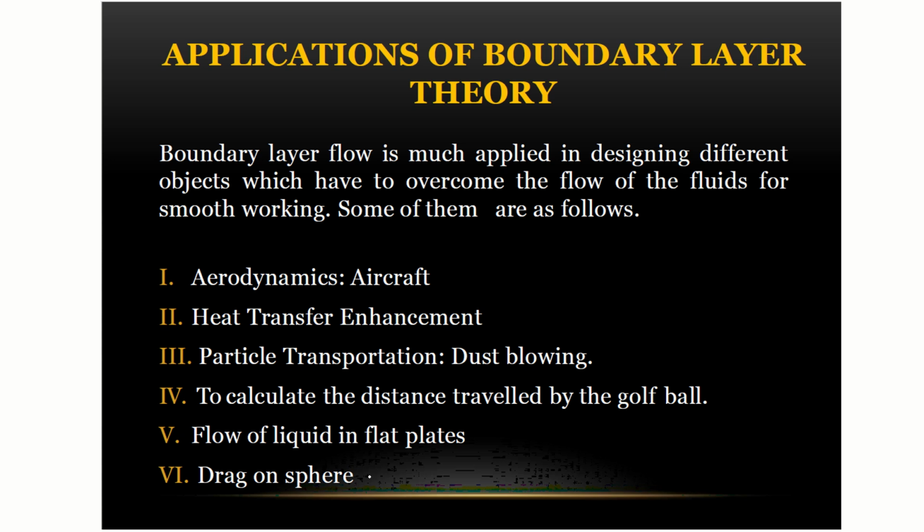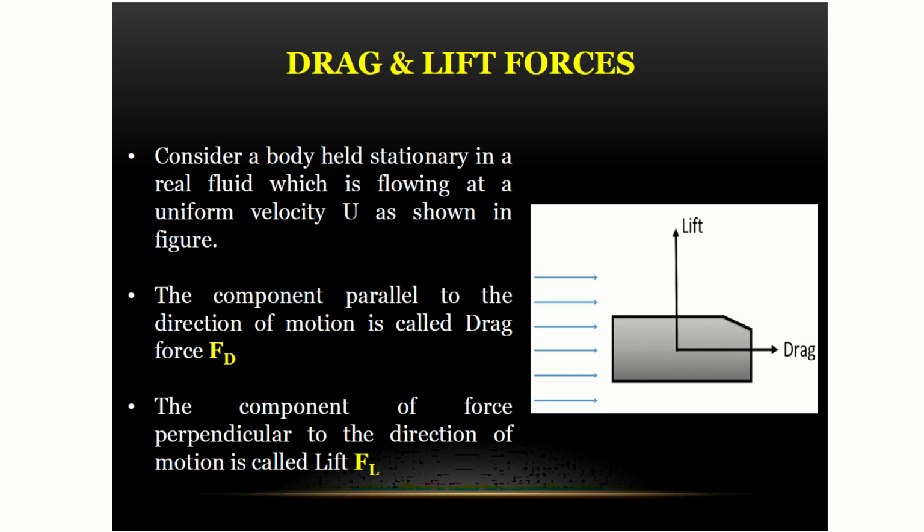In the context of drag on a sphere, the boundary layer affects the flow separation point, which in turn influences the drag force experienced by the sphere. The nature of the boundary layer, that is laminar or turbulent, can determine the amount of drag, with a turbulent layer typically reducing drag compared to a laminar one due to delayed flow separation. So these are the applications of boundary layer theory, and our today's video is about the calculation of